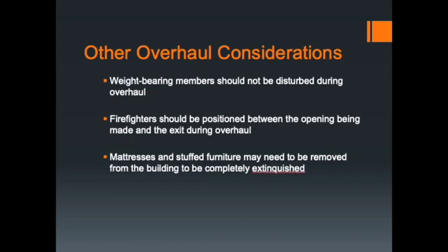So watch out for weight-bearing or load-bearing members during your overhaul operations. Where I'm referring to this is floor joists, whether they're from the basement to the first floor, or floor joists from the second floor to the third floor, or any interior vertical structural components. Just be cautious with those. If they are involved in fires, just be cautious working around those. If they're burnt through, that's just something you want to make aware to everybody, because that's ultimately keeping the structure up. And if one of those fails, it could be detrimental to the entire crew working inside the building.